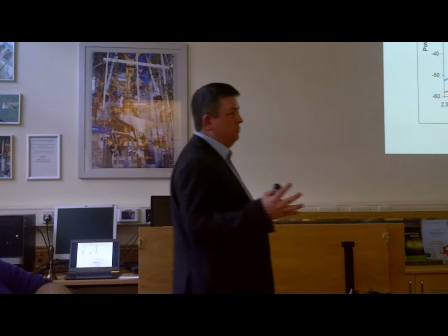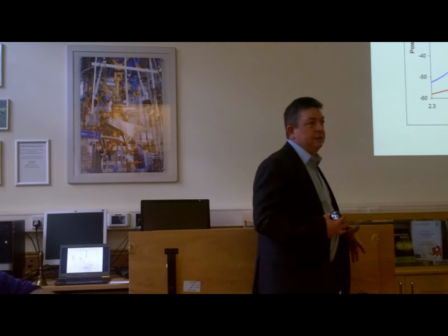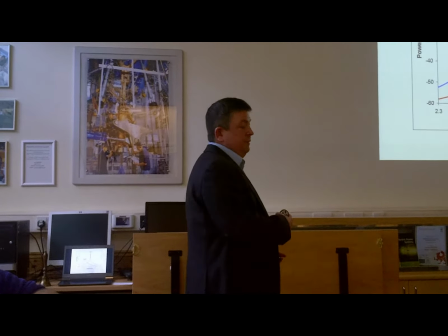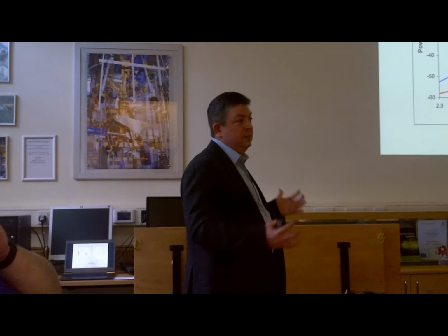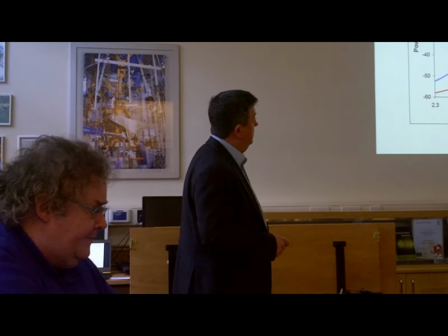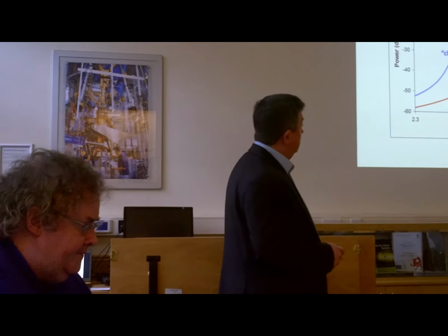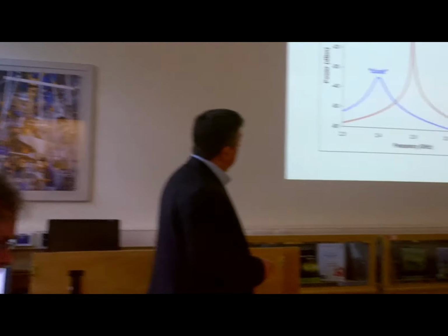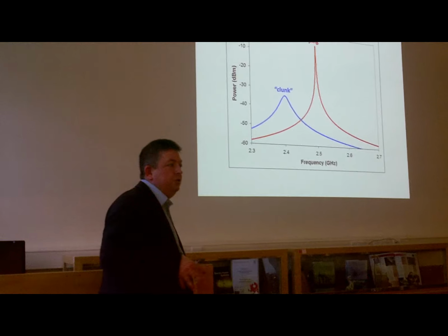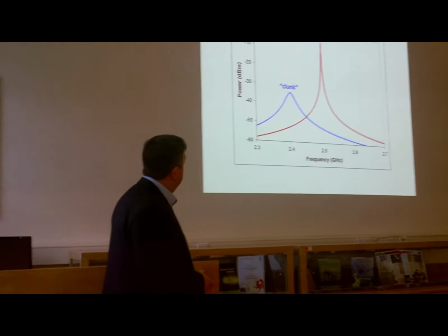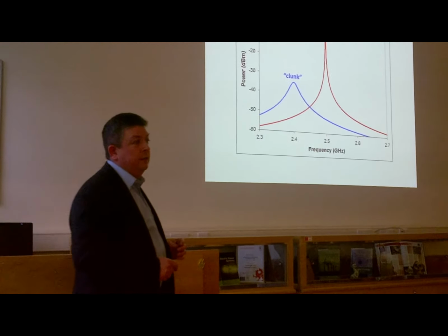They're high Q structures. Of course, if you damp this, then instead of hearing a ping, if I hold it, then it clunks rather than pings. And of course, the spectrum of a clunk is something which also involves absorption. So if you look at the spectrum of a clunk, you see two things. One of them is that the bandwidth broadens. The other thing is that the frequency shifts. It doesn't have to shift downwards, as I'll show you in a minute, but generally in these sort of acoustic resonances, the frequency moves downwards.